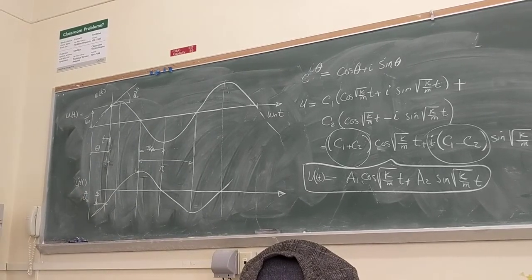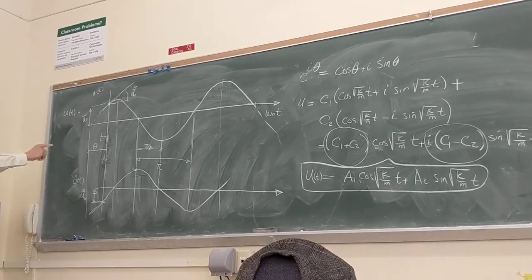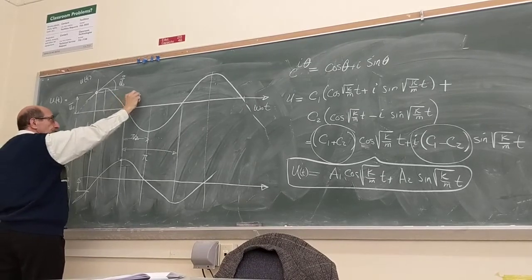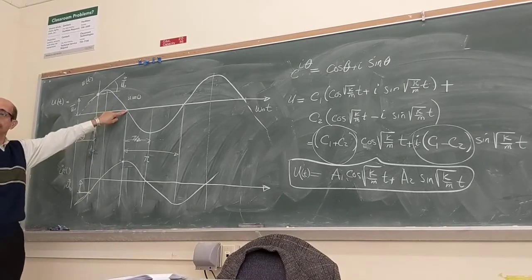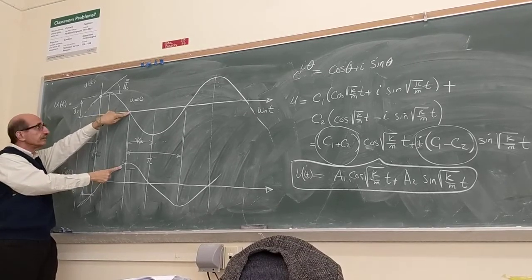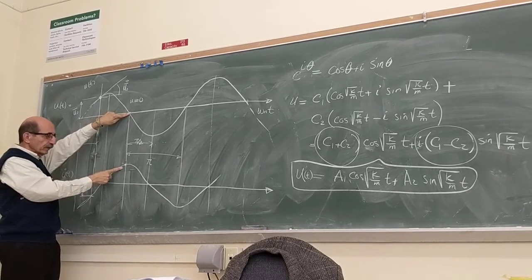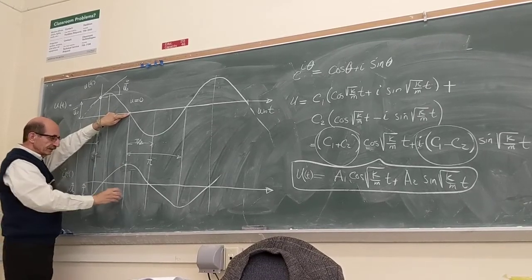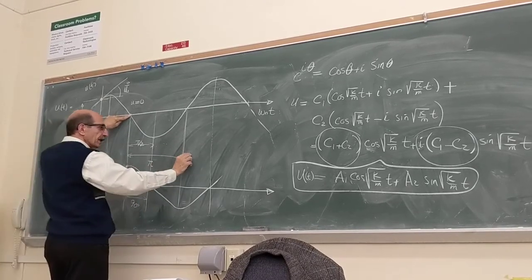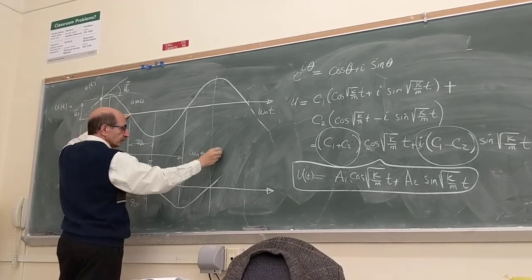But the beauty of it is, now if you look at it, what it means is when displacement is 0, okay, velocity is maximum, right? And for the velocity, it takes omega n t equal to 90 degrees, or pi over 2, doesn't matter.